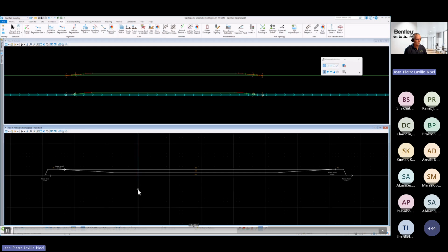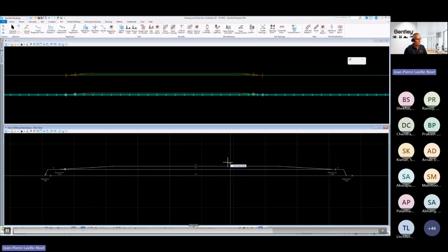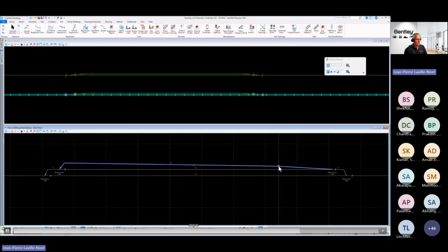So it comes like this, but we can manage the schematic view to move, for example, the edge. Here we are mirroring the edges to get the schematic more understandable, more common. We can move the points like this, snapping to the grid, for example, to create a nice schematic view.